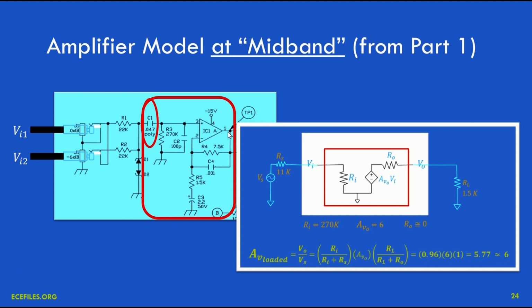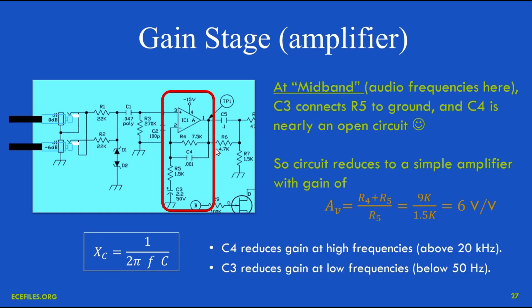And that's important because it means that no matter what we connect this signal at the output here to, within reason, it won't form any significant voltage division. So whatever we found for the gain from the inputs up to this point is not going to be affected by what we connect here. So this 4.7K, this 1.5K, this 0.1 microfarads, we can ignore all of that when we're analyzing what goes on here.